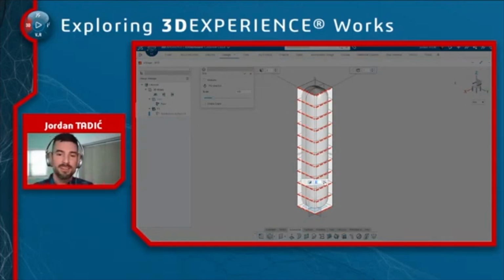I always relate it to sketching splines. If you've ever sketched a spline in SolidWorks, you know that you don't want too many points, because then there's just too much to control, but you don't want too few, because you need the level of detail that you need. So here I'm choosing 10 because if we look at the finger, the first stitch is kind of like a 3-point arc, right? You've got a point up here, a point in the middle, and a point at the bottom.